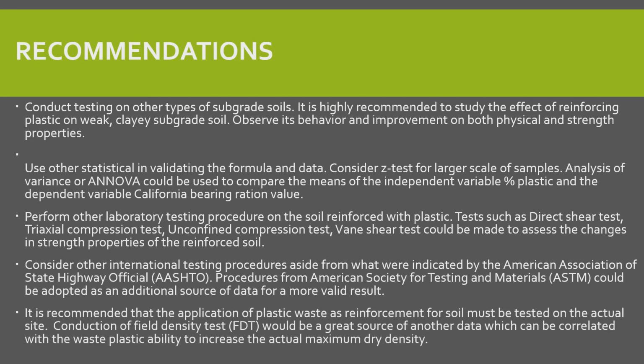And lastly, it is recommended that the application of plastic waste as reinforcement for soil must be tested on the actual site. Conducting the field density test or the FDT would be a great source of another data which can be correlated with the waste plastic's ability to increase the actual maximum dry density of soil.